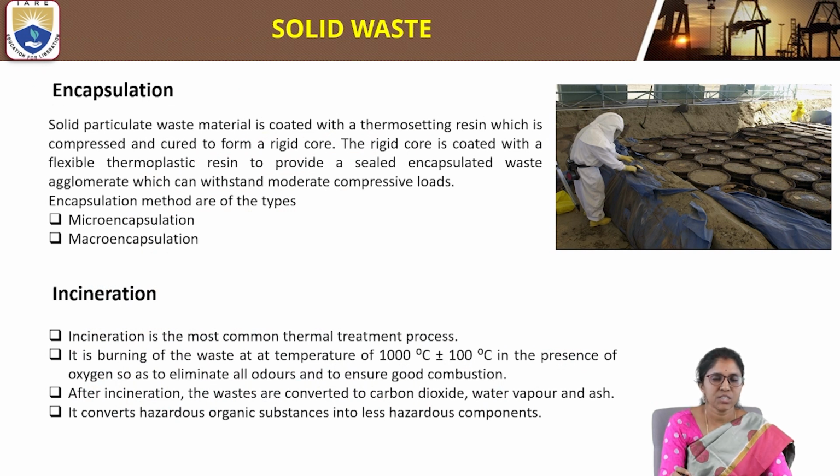The next process is encapsulation. This is for solid particulate waste material. The dangerous, toxic solid particulate waste material is coated with a thermosetting resin, which is compressed and cured to form a rigid core.